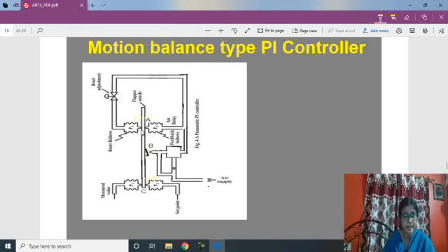At that time C acts as a pivot, because there is no further change in pressure between these two bellows elements. So C acts as a pivot and A will move towards the left. As a result, B will also move away from the nozzle direction. So in the next level, the nozzle feedback pressure will decrease. That is the effect of the proportional controller.